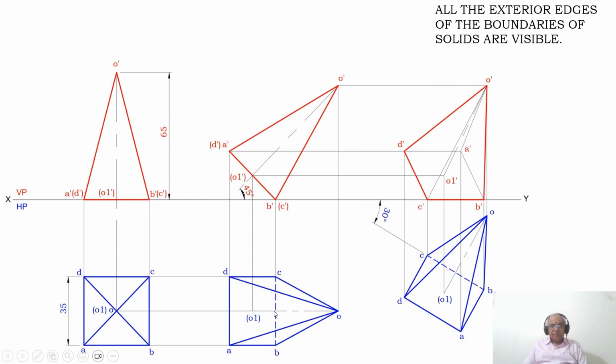Then you measure the distance from this point to O. From this point, transfer it onto this line, so you mark that point as O. From O, by using the compass, you measure the distance from O to O1 of the second position top view. From O, you cut an arc on this perpendicular line and you mark that point as O1 in bracket.